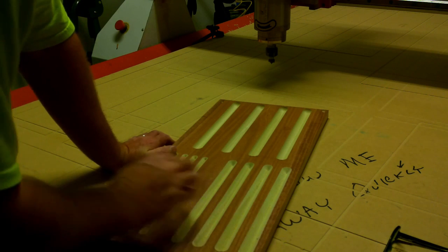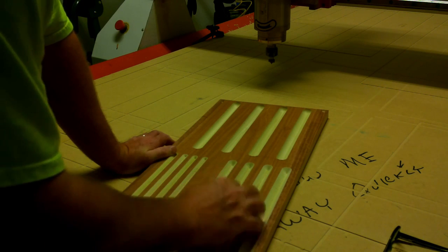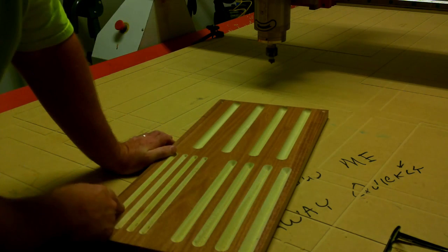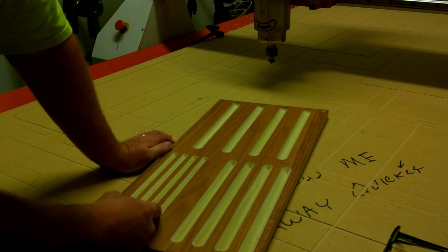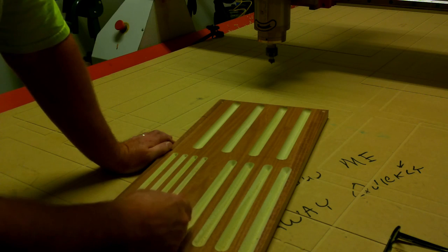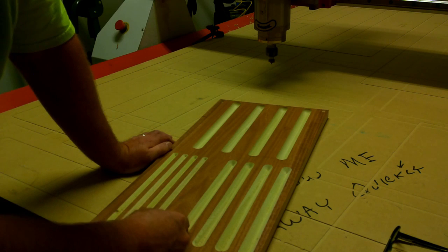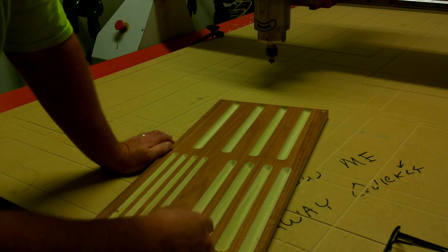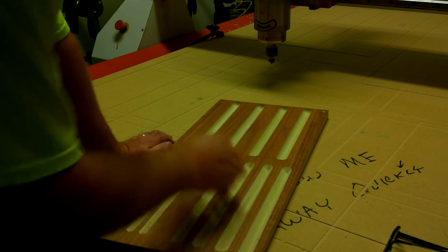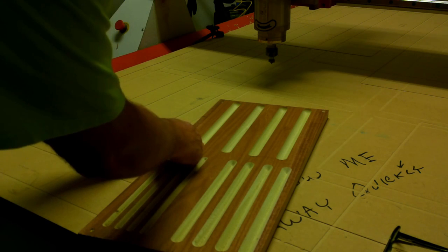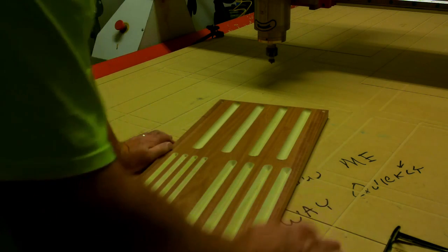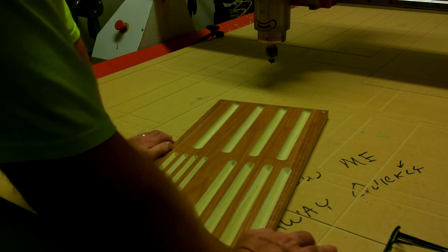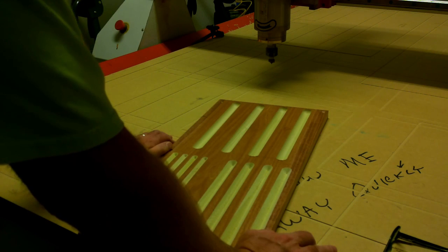There are 4 different speeds for 3 different bits. Okay, this is a pointed roundover bit starting at 12,000, 14,000, 16,000, and 18,000 RPM. This is a 90-degree V-bit starting at 12,000, 14, 16, and 18. And this is sometimes referred to as a core box bit or a roundover bit, at 12,000, 14, 16, and 18. Now, if I were to judge just overall by glancing at the quality of the cut, core